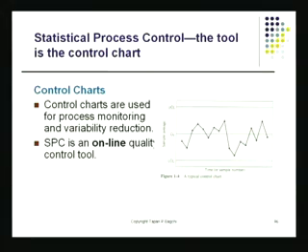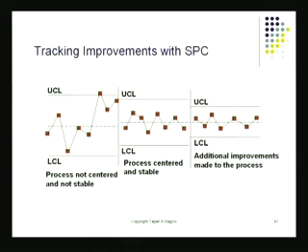And what is the result for doing all this? If you start with the process, look at the distribution on the left hand side. It's wide. That means perhaps my product is probably out of specification occasionally. I should just remind you that here I've got control limits. I don't have spec limits, because what I'm plotting here is some variable like X bar or R, which are really statistical in nature. These are not individual measurements.